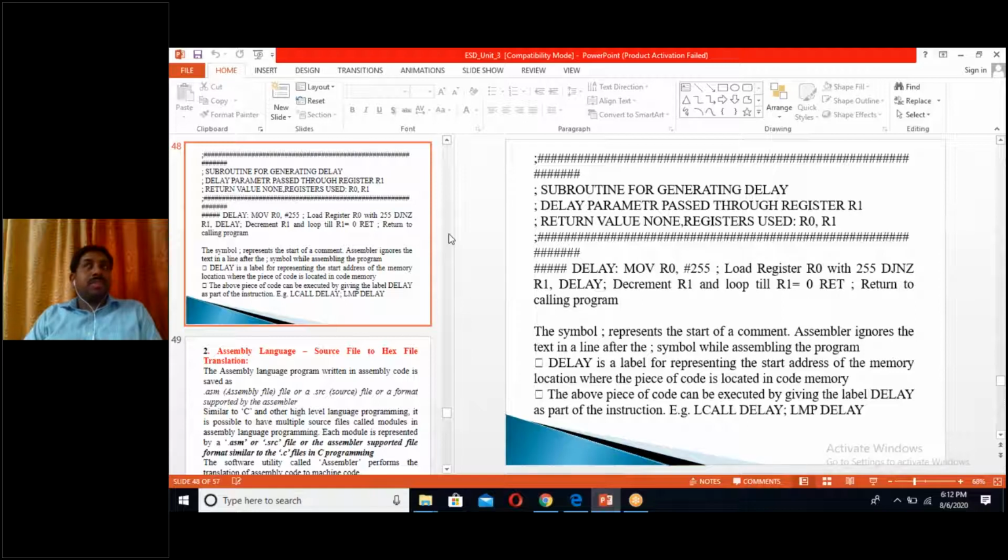First one is embedded C, C++. Second one is assembly language. These two can take two approaches. One is the super loop approach, where it is written as a set of tasks and there is no time criticality and no priority. But when you go for embedded OS, we can go for a real-time OS where task priority and task scheduling are done, compared to a general purpose OS. So with this, I'll stop my session.